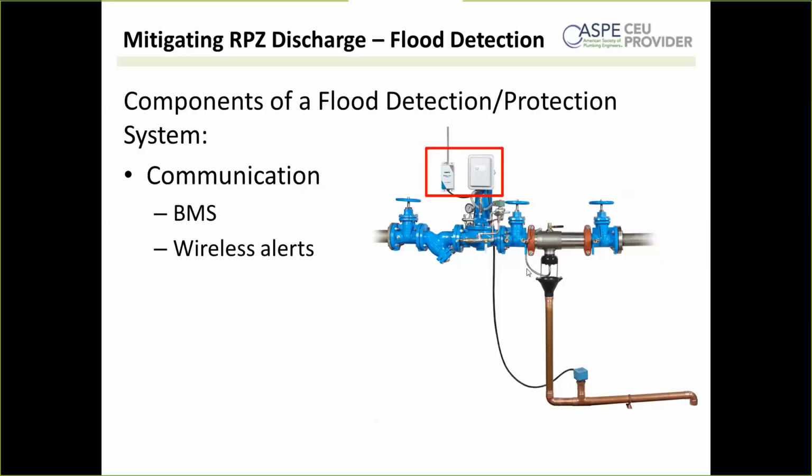It's nothing standard. You have to typically pair the recommended air gap with that backflow preventer. And also, those air gaps carry their own approval. So there's actually an ASSE test for those air gaps, and it's that air gap with its intended backflow preventer. So yes, please do use the manufacturer's recommended air gap.